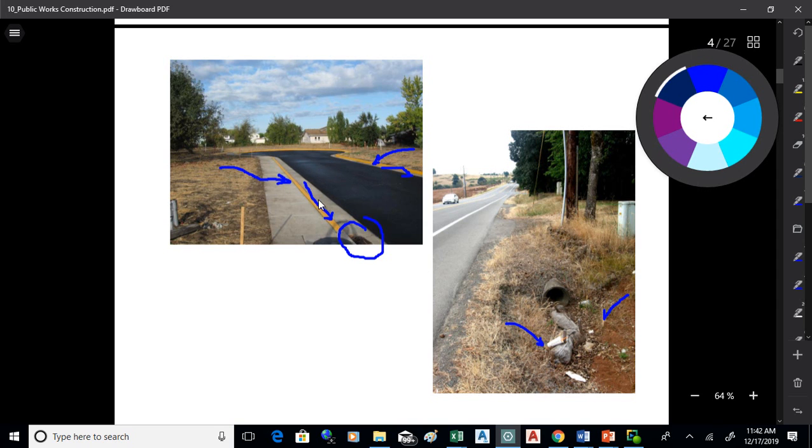Once it's into the gutter, we can then slope the gutter into these little what are called catch basins or curb inlets here, and then get the water into pipes so we can carry it away to what we call the receiving streams, in this case the stream or the river. So the approach on this again is to design these roads down into the ground a little bit so that the gutter will serve as a drainage conduit for the surrounding area.